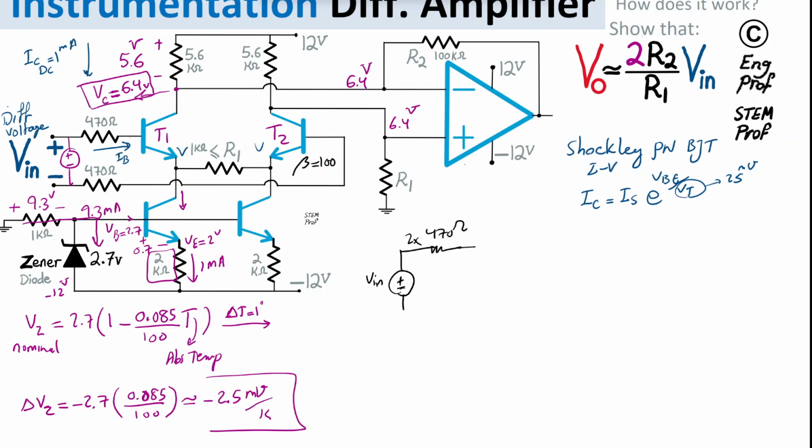Then we have 2 times the base resistor, HIE of the transistor, for the AC small-signal analysis. It's 2 times because we have the T1 and T2 transistors here, and that HIE is observed from the perspective of the base.